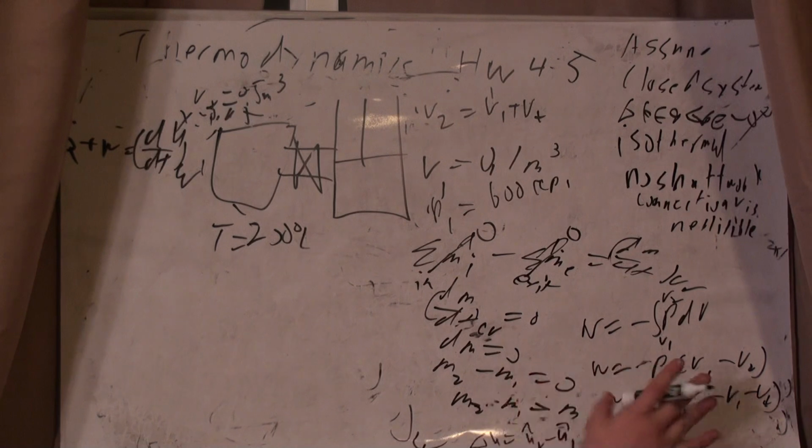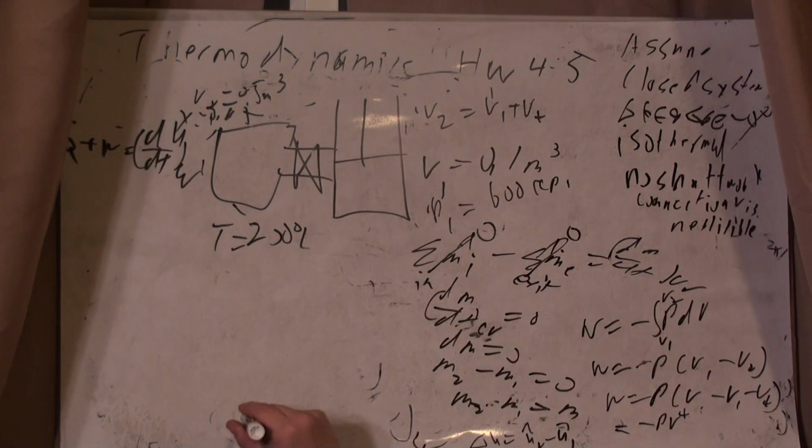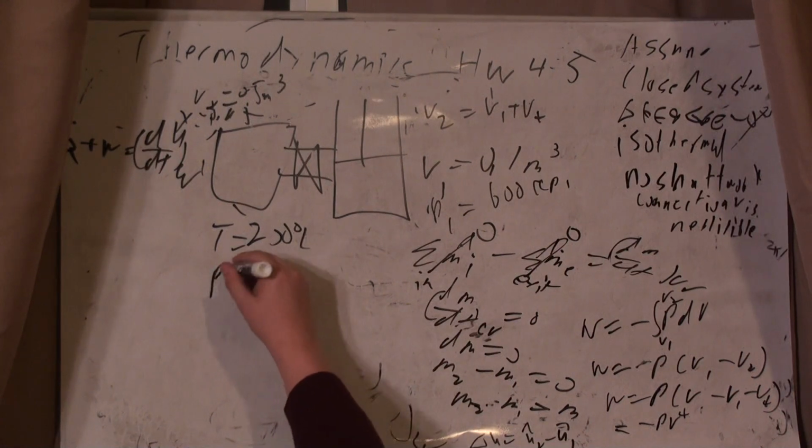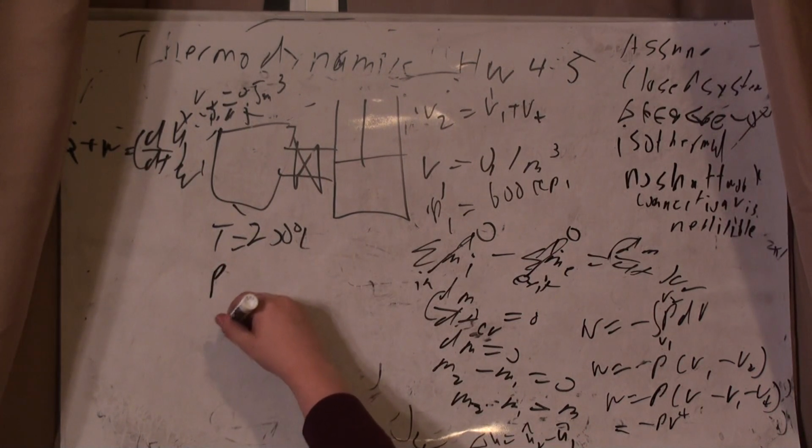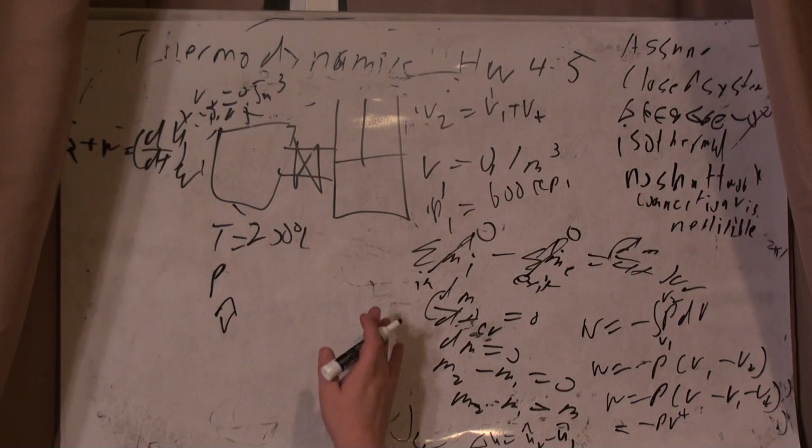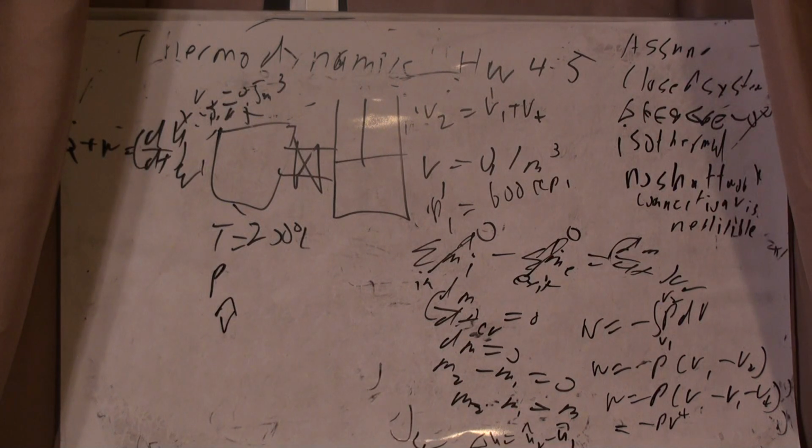So the pressure is constant in this case. The pressure is going to equal 600 kPa when we're said and done. It doesn't really matter the quality other than it's going to tell us the mass of what we start with. Because we know the temperature and the pressure, we need to get the specific volume. The specific volume doesn't change, but the mass is what's really changing here.